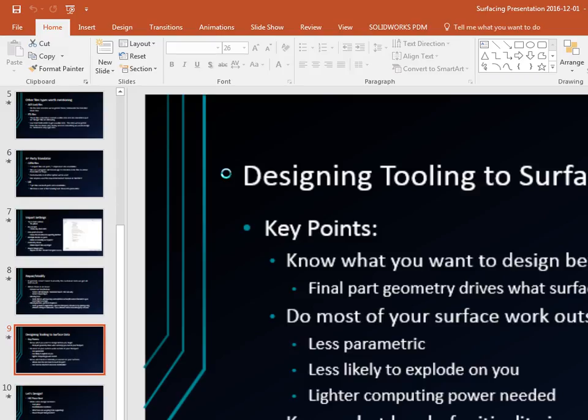So offset those surfaces, edit part, and offset to do my 0 cuts there. Like your keyboard surface that you wanted to actually set on, I'd offset that 0, but then the clearance on the side, maybe 2 or 3 thousandths, I'd offset those surfaces. Then I go to my part, do all my extends and patches and stuff, and then cut at the part level.